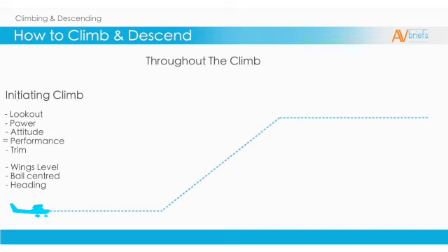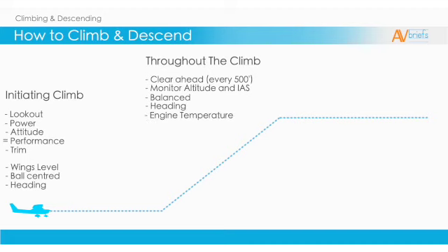Throughout the climb, clear ahead every 500 feet. Monitor your altitude and indicated airspeed. Ensure you are balanced with the rudder. Check heading. Monitor engine temperatures.